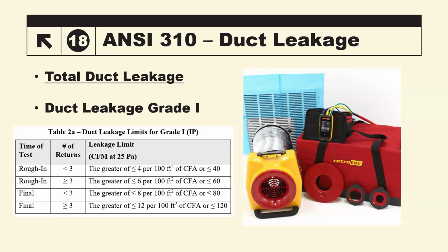So, not to throw a wrench into anyone's rating business, but if you want people to do 4% total duct leakage, regardless of their compliance path, whether it's one of the normal ones in the IECC, whether you're in Texas doing the Energy Star compliance path, or you're doing the HB 3215, you need to make that explicitly clear with an addendum or something like that.